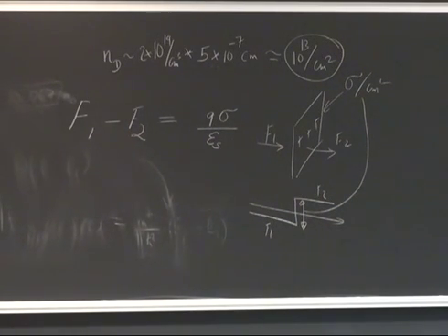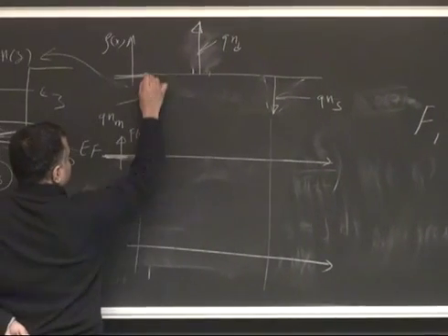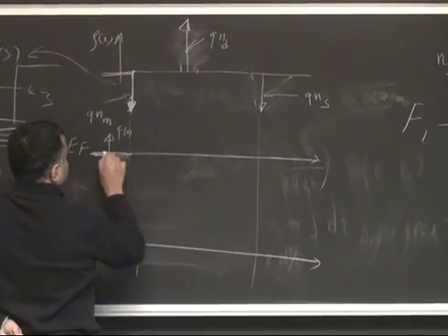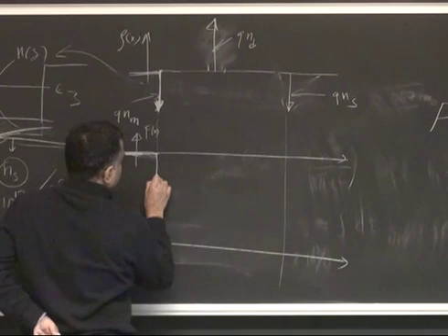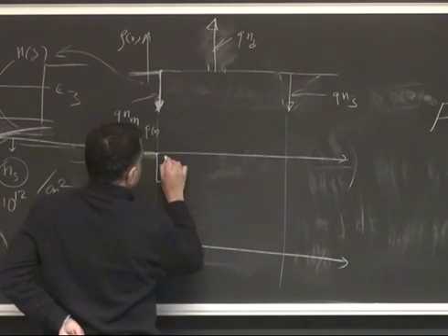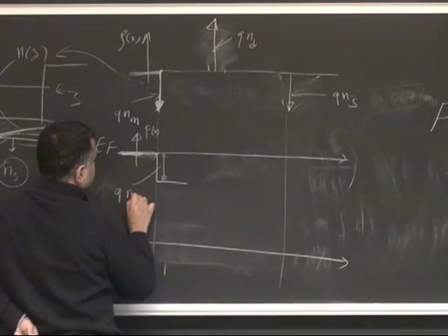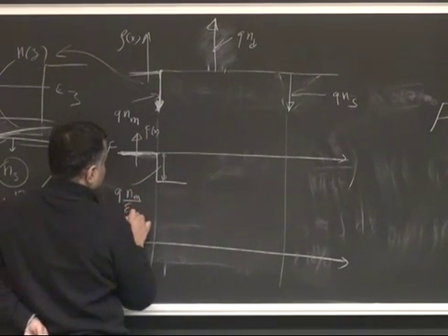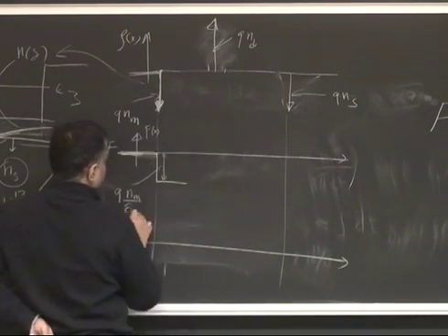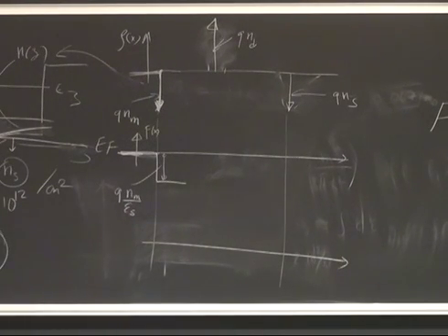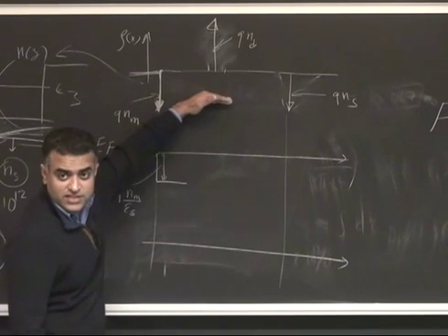So as a result, you see that the field here, I have negative charge, and I have 0 field on the left, and when I go across the junction, the field is going to abruptly jump by Q times N in the metal over the dielectric constant, not in the metal but in the semiconductor. It's always the insulator part of it. So that's the field that is in this region. Does that make sense?